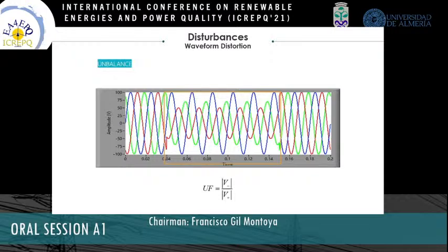Therefore, many power quality indices affected by these power quality issues are tackled, including the RMS voltage, the total harmonic distortion, the distortion index, the crest factor, the displacement power factor, and the true power factor. These power quality indices are crucial in representing, quantifying, and comparing complex power quality phenomena.